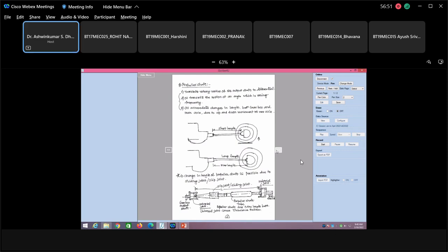This unbalance problem is due to the sagging of the propeller shaft in the in-between area between the two joints. So the propeller shaft, being usually rolled out from a flat sheet, is straightened within 0.25 mm runout.